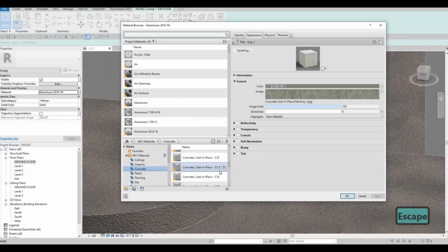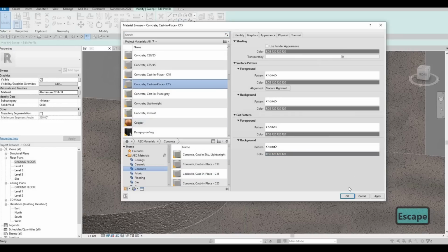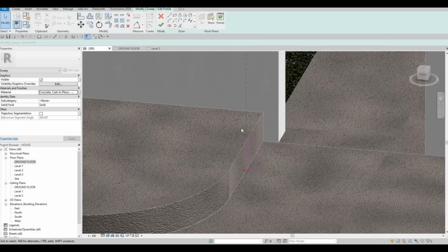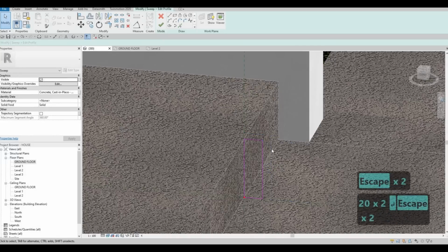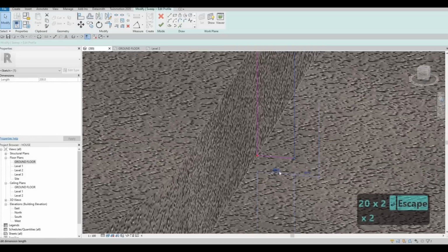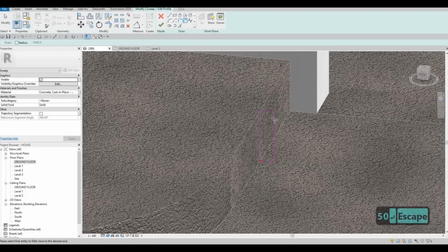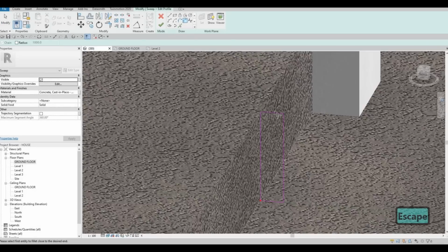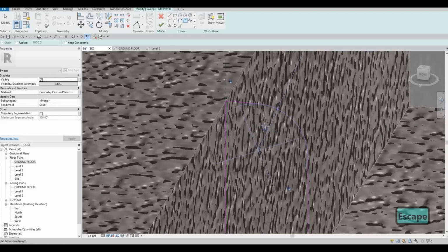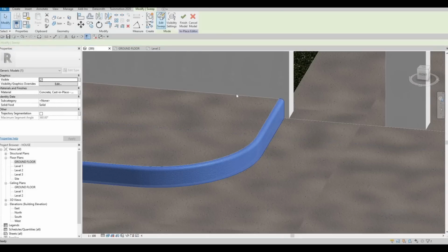This one you need to know, so this one, so C15 of this cast in place, so C15. And then here we need to change the height to 200, and then here this one is around 50, and then we're going to fillet arc this one. This one is around 30. That's good enough. So here we're gonna click on finish and then finish again.